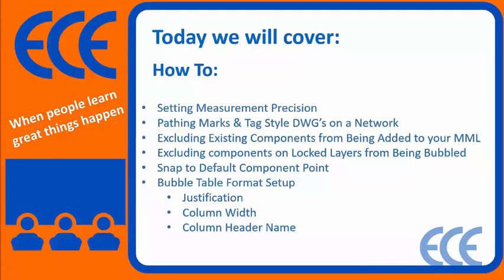We're going to look at a couple of settings here. We'll set the measurement precision. We've gotten feedback from customers that when a pipe is totaled up, sometimes they get 16ths or 8ths of an inch. So we'll see how to make that measurement precision come down to a 1/2 inch using architectural units.